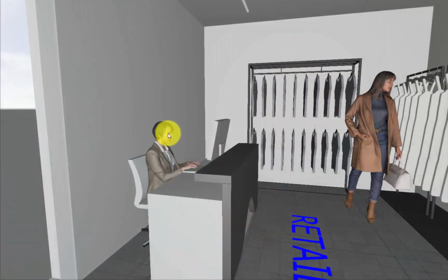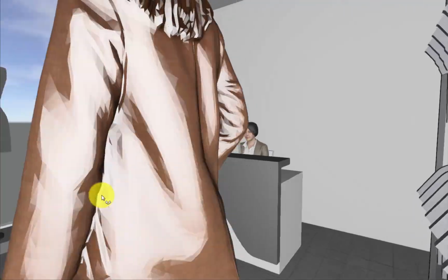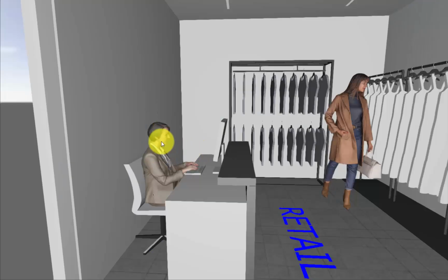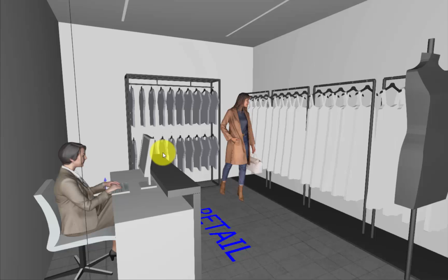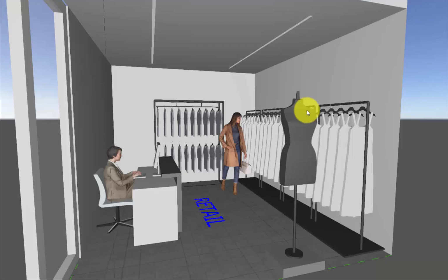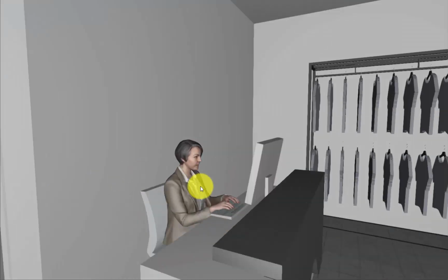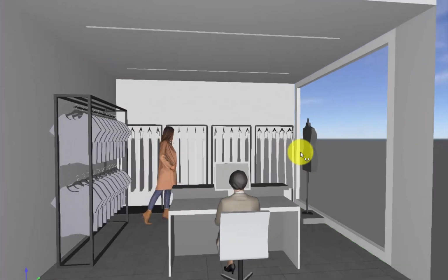So her facial expressions, her face should be properly lit so that the people can engage better, right? And the receptionist is 3D. We need to make sure she is properly visible from anywhere in the retail. And for that reason, here too we will be doing cylindrical illuminance. Okay, in this project, we will be doing cylindrical illuminance for 3 objects. 1, the mannequin. 2, the people, customers. 3, the receptionist. Okay, now let's see how to do the cylindrical illuminance calculation in DIALux evo.